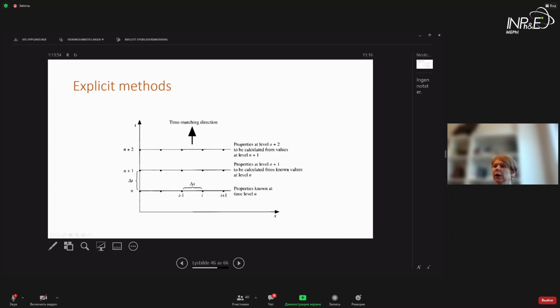This is going from step in time, step number n. We are introducing time step delta t, and with the time step we propagate our solution to different steps in time, n+1, n+2, and so on. And for every time step, we are solving the equation on our spatial grid. Here, for simplicity, only the x coordinate is drawn, but we are going to look at both x and y. So for every time step, we have to cover the xy grid and solve the equation there, loop through all these grid points, and when we are finished, then we are ready to propagate to the next time step.